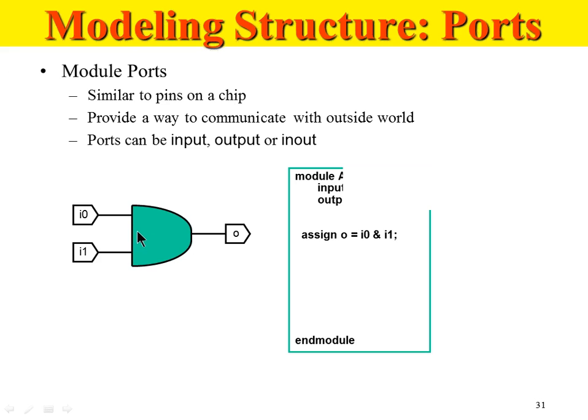Okay. So now we saw that we can build hierarchical or bigger designs using basic blocks. Using this two input AND gate, I am going to generate a three input AND gate. For that I need two such AND gates, and this is how I will build a three input AND gate. The first input of the three input AND gate goes to the first gate, and the output of this AND gate goes to the input of the second AND gate. The third input of the three input AND gate comes here. This is the final output that goes out.